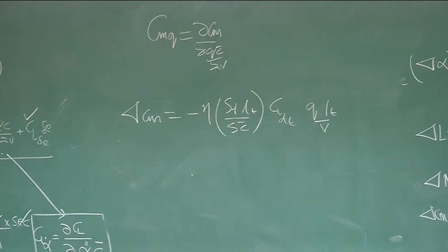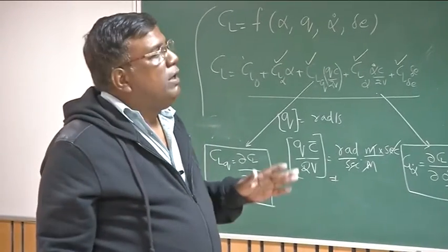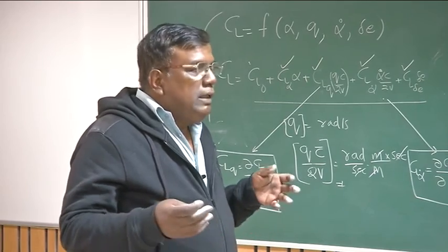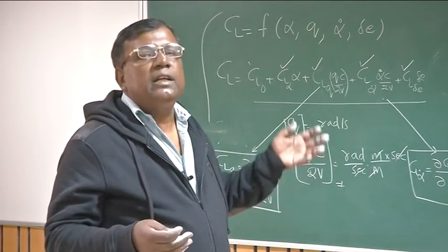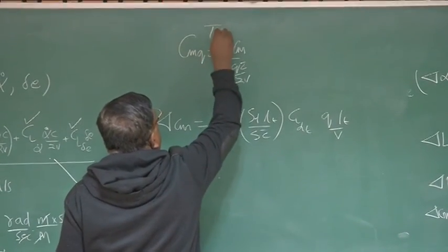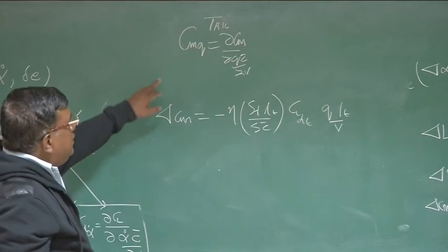contribution. So we have to similarly find out the contribution because of fuselage and wing, but we are trying to find first the expression for tail contribution, because we know that is the primary component which will add to these derivatives, right? So this is, of course, I repeat, we are all now focusing on the tail, which is the horizontal tail. So now our aim is to get CMQ.